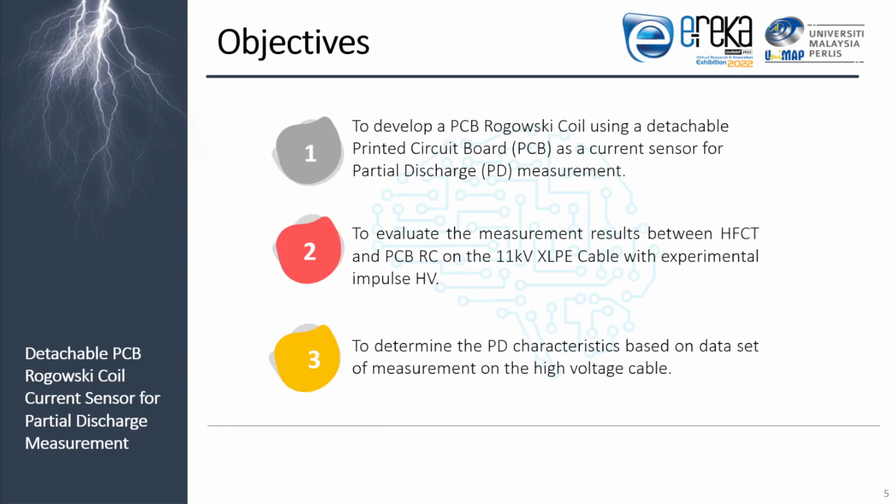Okay, and here is the objective of my project. First, we have to develop the PCB Rogowski coil using a detachable design. Why detachable? Because of easier installation on site, and we can bring the equipment to any location, so then we can measure in any location.